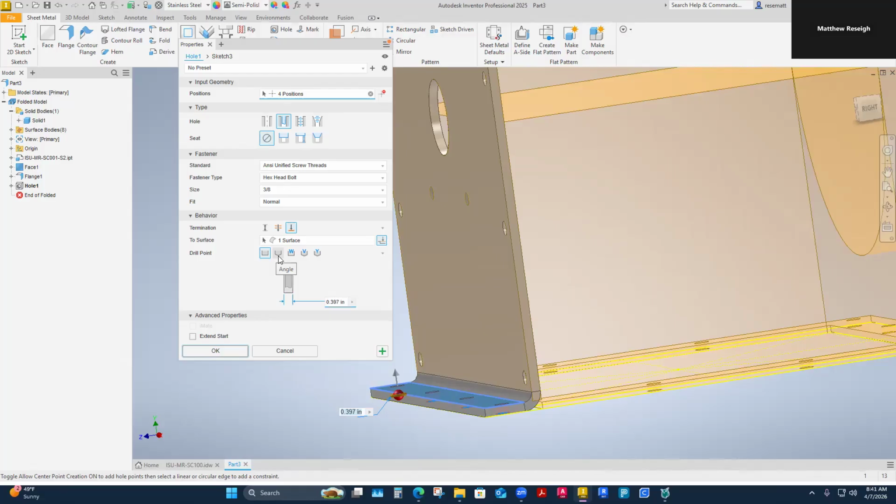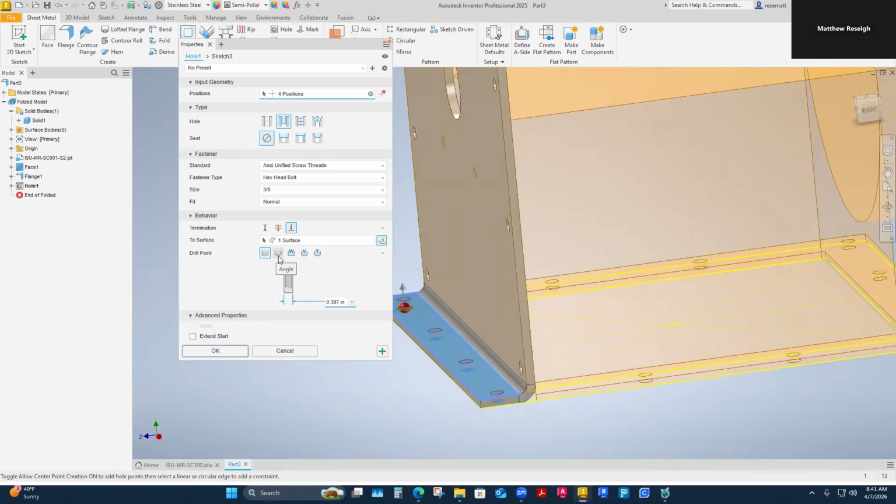We're threading in a fastener, and fasteners have to be threaded in the correct amount to carry the load. You have to use the right size fastener and have enough threads to catch all the threads that are required to carry that load. And so those blind holes are really critical.